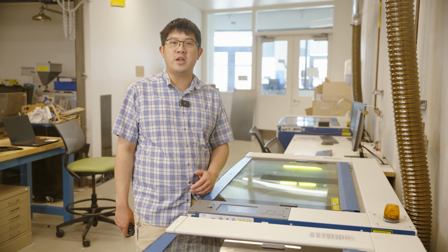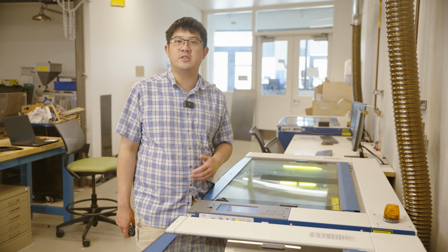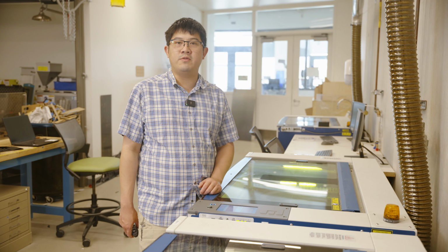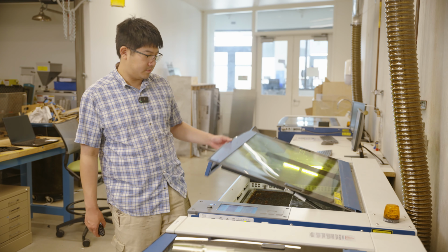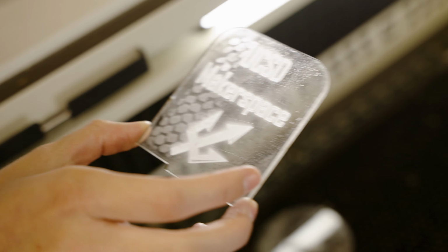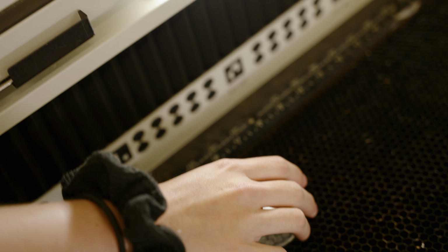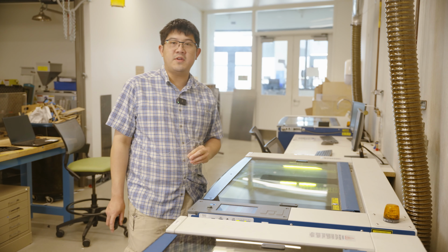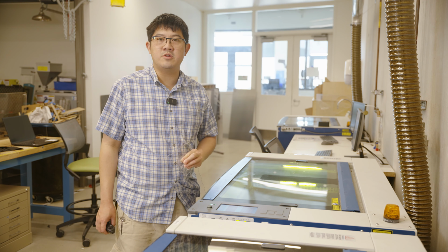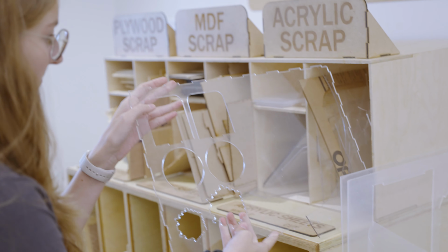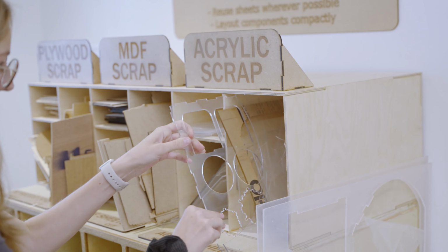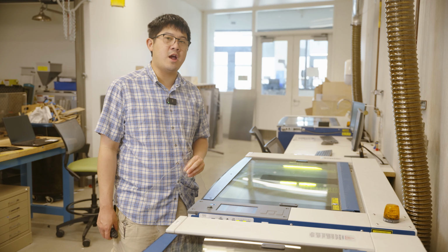Once the laser is finished cutting, wait around 15 seconds until the fan is turned off. Grab your part and remove the rest of the material from your machine. Dispose of any scraps and put the rest of the sheet back in the organizer. Please cut down or dispose of sheets that are unlikely to be useful to others. We are here to help you with the equipment, not clean up after you.